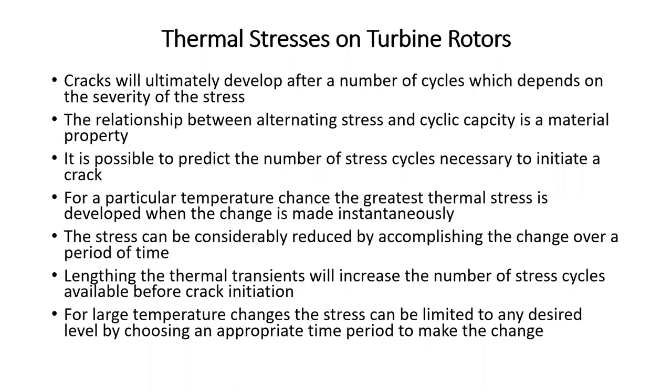For a particular temperature change, sorry, the greatest thermal stress is developed when the change is made instantaneously. That's the most potentially damaging way. But if it's a small temperature change, then that's not necessarily a problem. If it's a large temperature change, that could be a significant problem.